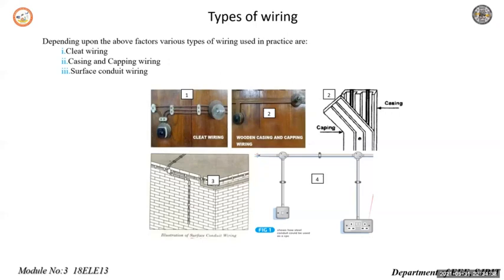The rigid conduits are always terminated at outlets into a box, which may be round, square, or octagonal. These boxes are used to provide connections for lights, fans, heaters, etc., and are called outlet boxes. Inspection boxes are used to facilitate the pulling of conductors, while junction boxes are used to house the junction of the conductors. This is about conduit wiring.